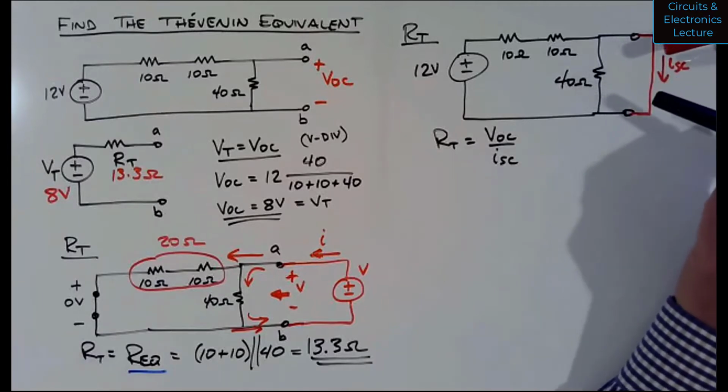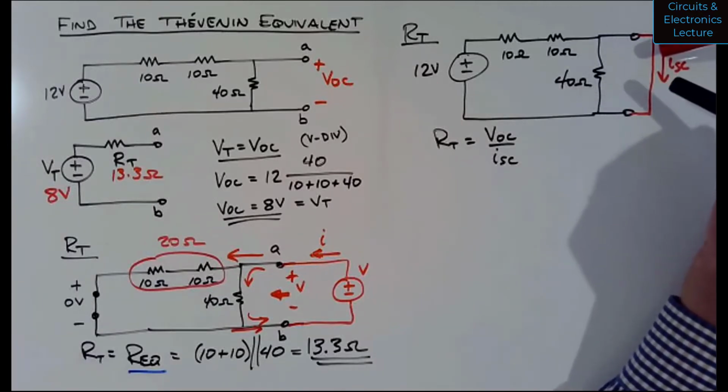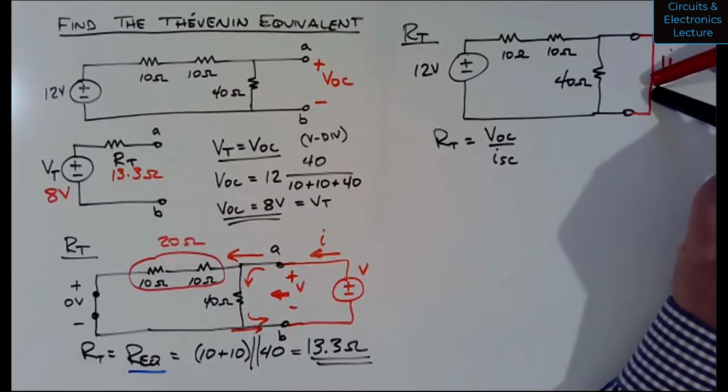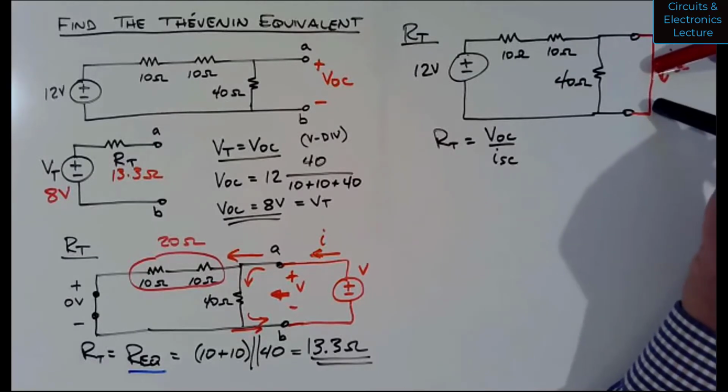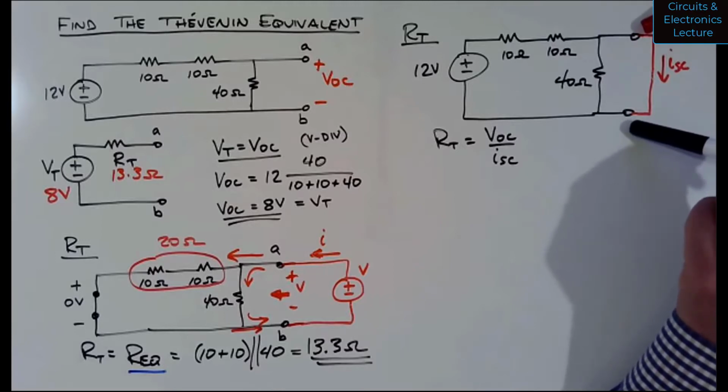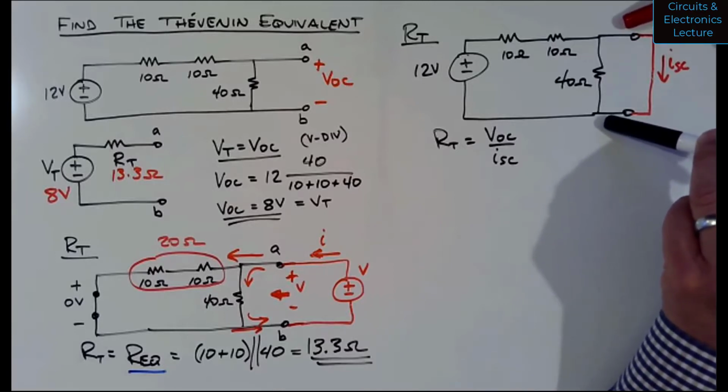Take your voltmeter from your AD2 and connect it to a node that maybe has 5 volts, even a power supply node, and connect the other terminal to the same node. You'll see about 0 volts, maybe a couple millivolts. So if I touch my leads of a voltmeter to the same node, I will always read 0 volts.